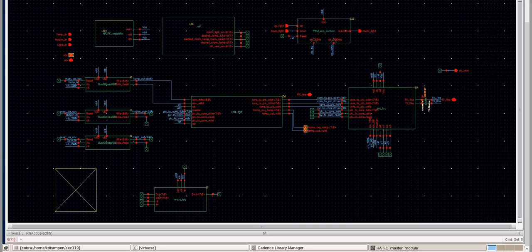Okay, my name is Tim. I designed the powerline communications module of this chip. So the scheme I employed was frequency shift keying, which encodes digital data as a sequence of pulses of varying frequency. This is so the resulting tones can be superimposed onto the existing power lines within the house.